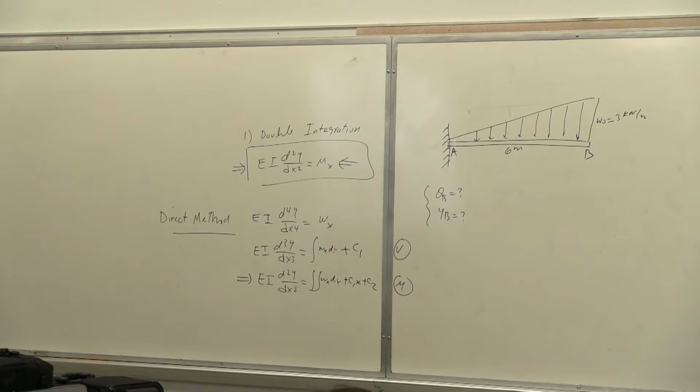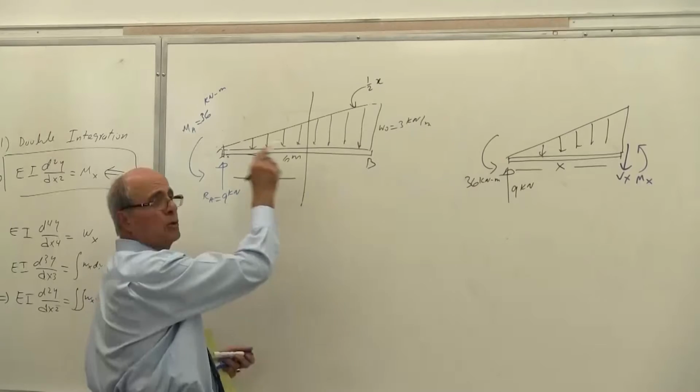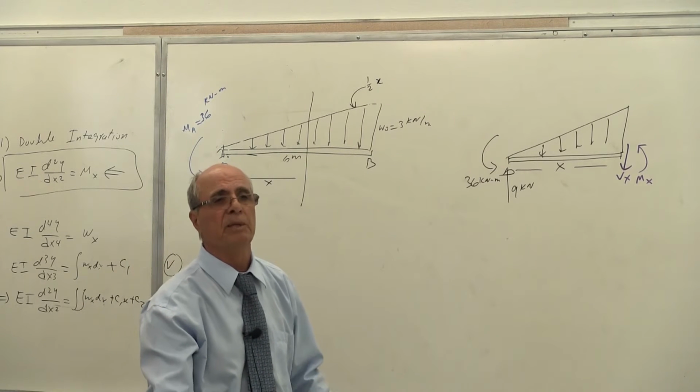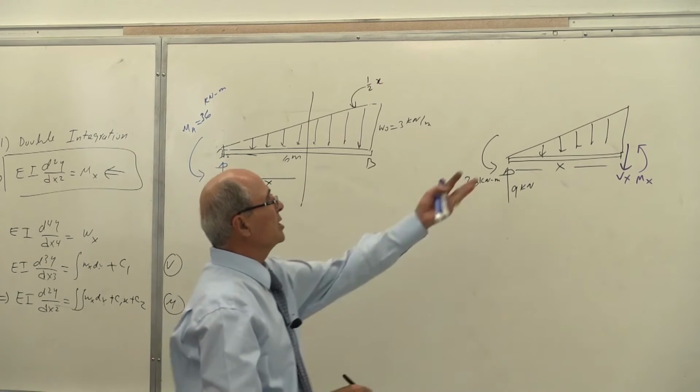And then you put here, let's put it in a different color, internal. Now we are in the body. So this is your load, and here is your shear as a function of x, and this is M as a function of x, because this distance from here to here is x. Is that correct? What is the change limit of x? x changes between 0 and 6, because I can only use one function for the entire beam. Yes or no? Correct?